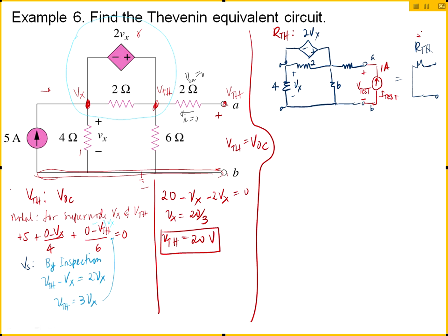What we're doing is really this: we know that it's equivalent to a single resistor. So if you look at the right side, if I apply a current source here, that will develop a voltage across it, and the voltage divided by the current I apply will be numerically equal to R Thevenin. That's basically what we're doing. Does that make sense? If indeed the black diagram here is equivalent to the black diagram here, which is just one resistor, whatever I do on the left diagram will be exactly what I'm going to do on the right side. And if I apply a current source, that will develop a voltage across the current source, and the ratio between that voltage and the current will be numerically equal to R Thevenin. Do you agree with this?